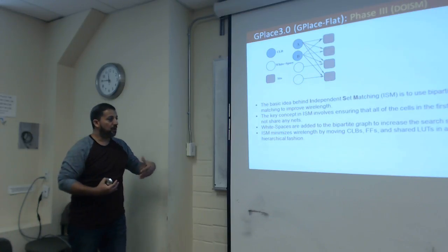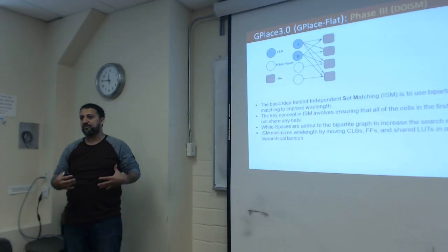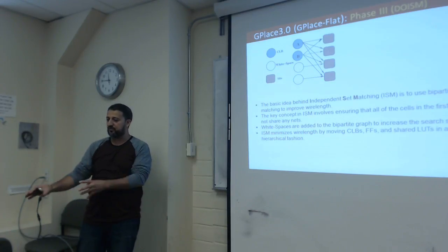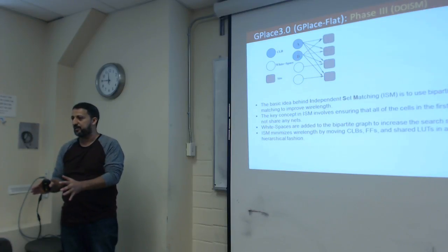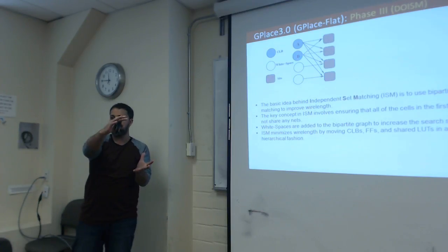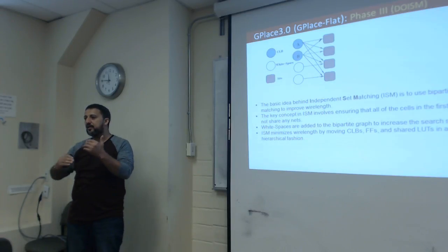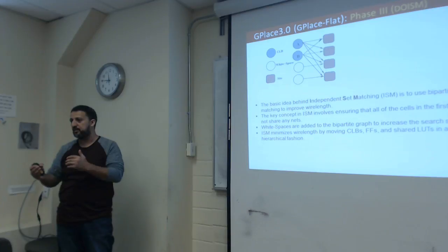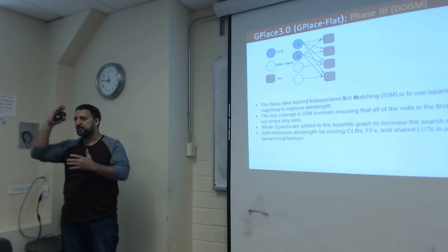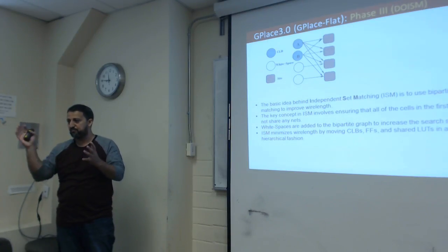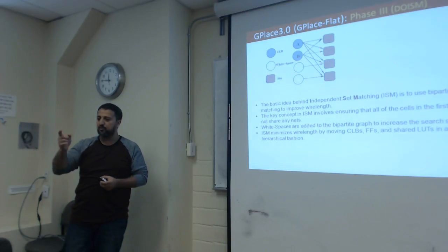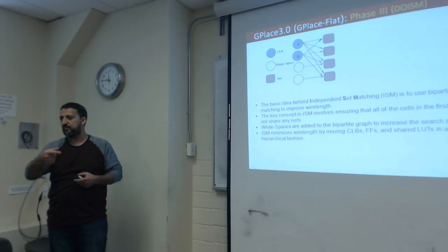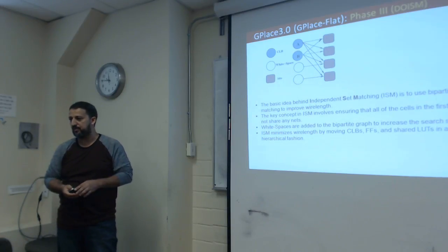Okay. Why are we doing that? Because if we are only moving LUTs and flip-flops, we end up stuck somewhere in a local minimum. By moving a group of LUTs and flip-flops with CLBs, you can help to scale local minima, to jump to a different solution and locations, so you can keep moving, optimizing for LUTs and flip-flops to escape the local minima.